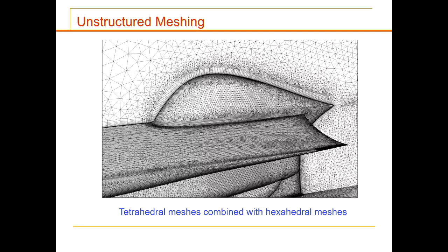To achieve the same accuracy, you tend to have to use almost 2 times or 3 times more elements compared to structured meshing. So if you want to compare apples to apples, you may use, let's say, 500,000 elements in comparison to 1.5 million for a triangular mesh. So that is the accuracy you have to think about. When you start thinking about that, you start thinking about computational run time. Because with a 500,000 mesh, you get a faster solution and more accurate than with 1.5 million.